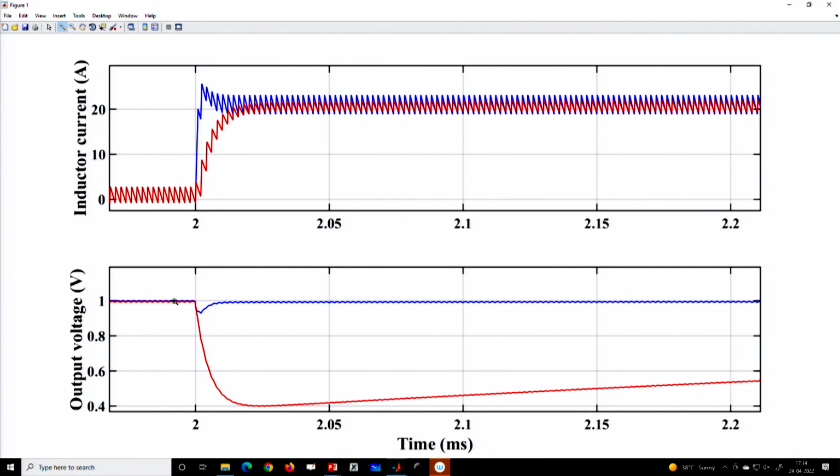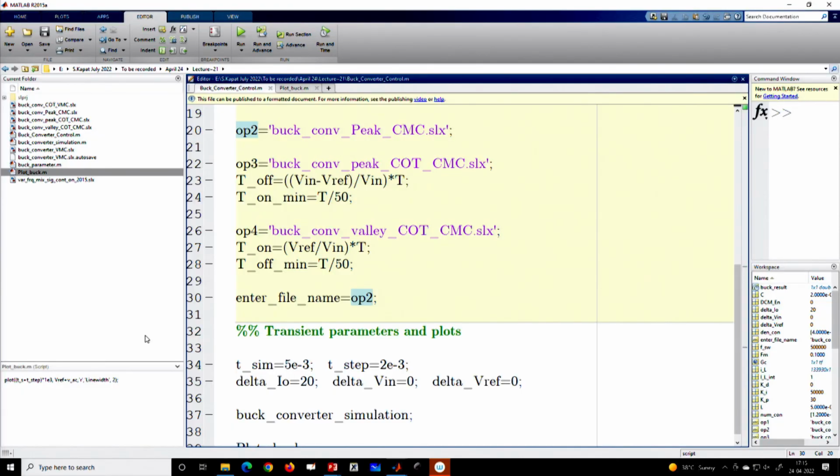But generally current mode control, we saw in our earlier course that the current mode control behaves like a first order system. So that's why it is kind of an over damped response. So unless you do load current feed forward, it will be somewhat difficult to speed up very fast within the small signal control bandwidth. So then we can also plot option 3.